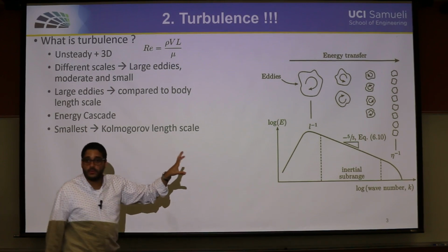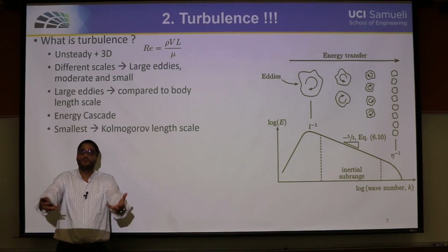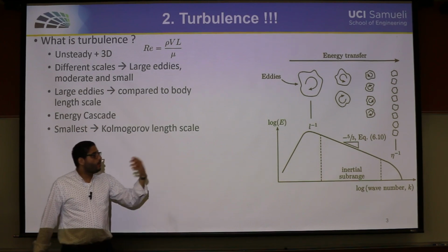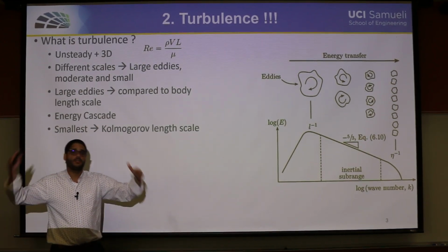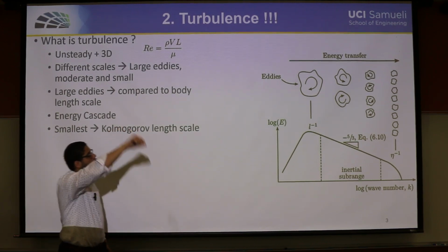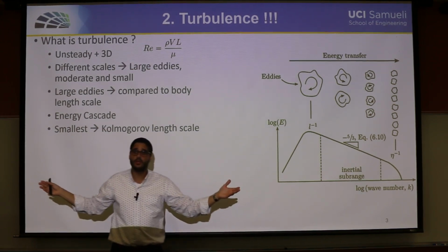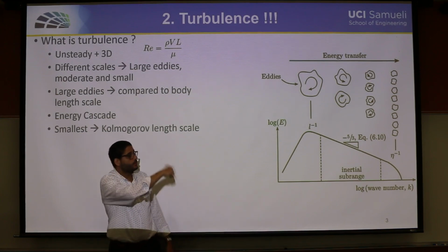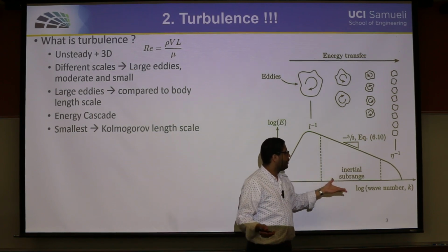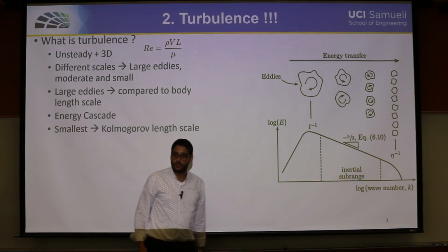And this is a very important thing. Why? Because if you are doing a turbulent simulation and you would like to judge the accuracy of the flow field, as we said before with y plus or other variables or the mass imbalance between the input and the output, you can have a single probe at a random location in your flow field, store the velocity, do that power spectrum analysis, and plot it. If your simulation is correct and the turbulence is simulated in a natural way, the slope of that line must be equal to -5/3.